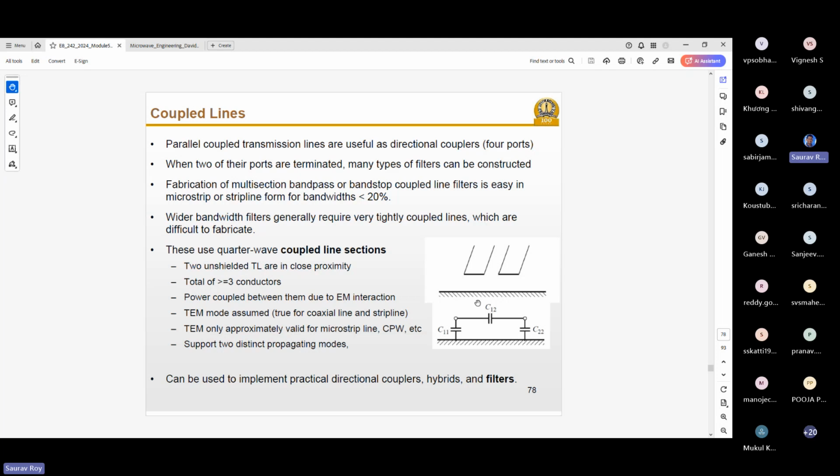So as you see, this simple coupled line has the ground layer as usual. And on the top layer, instead of one microstrip line, you are putting two microstrip lines with a gap. The equivalent circuit can be written as a capacitance in between them, and there are two capacitances from the top to ground through the substrate. Right.